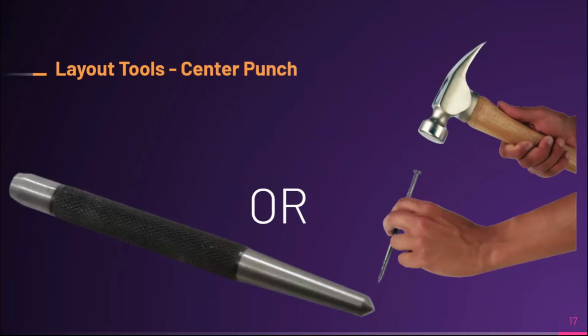One thing you'll want is a center punch. This is used to make a small indent in the center of wherever you want to drill. This is done so that the drill can more easily find its way and not slip and drill slightly off. This is especially prevalent if you're using a handheld drill. However, it does still help when using a drill press.